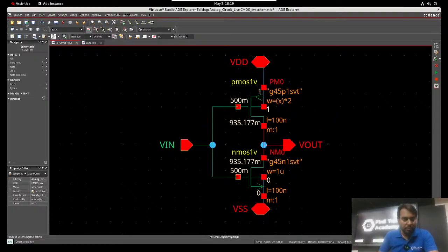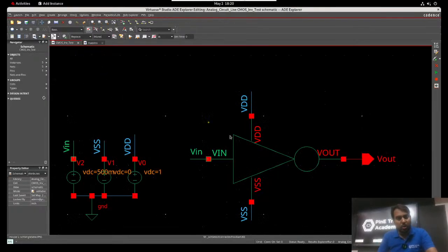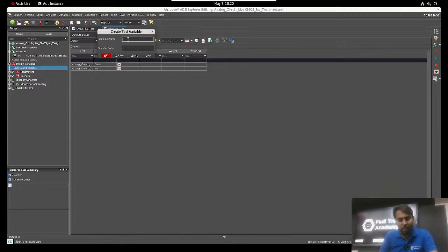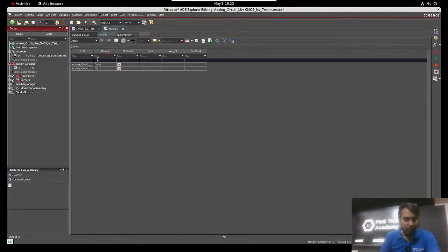Okay, and press Control E, so you can go back. Just press maestro here. Okay, so I am taking one variable. Go for the design variable, and you can put the variable X, and provide any value. Let me provide 1 micro.